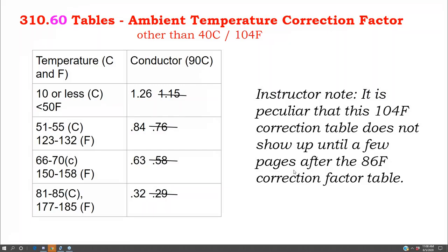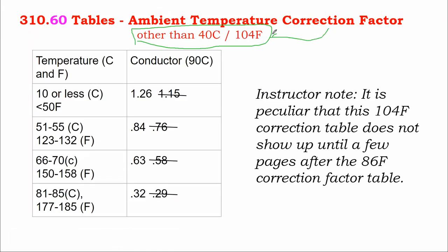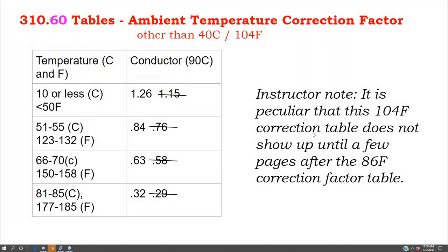Because a conductor in free air has much better temperature dissipation than inside of conduit, it will have a different ampacity rating than inside of conduit. So you have to read the chart title headings and make sure that the modifier in the title heading makes sense for your case.